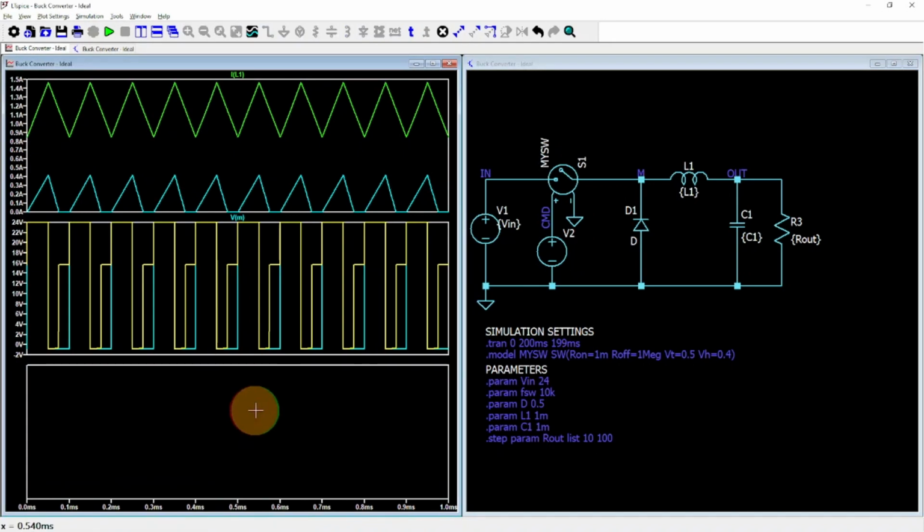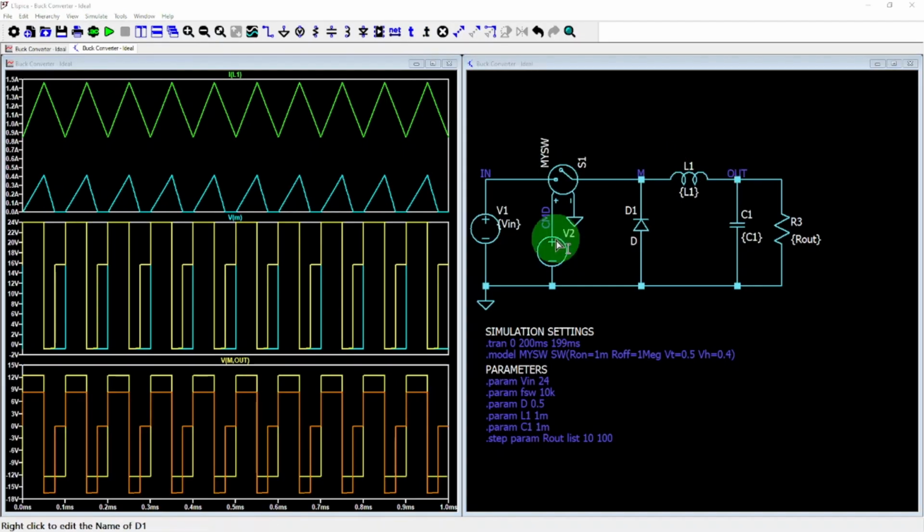If we check the voltage across the inductor, we notice something interesting. The intermediate voltage level appears in DCM. That's because when inductor current is zero, the voltage drop across the inductor is also zero. In contrast, in CCM, the inductor voltage is never zero during switching.